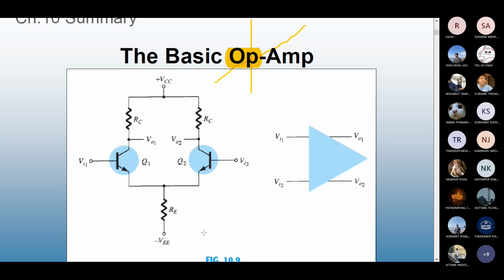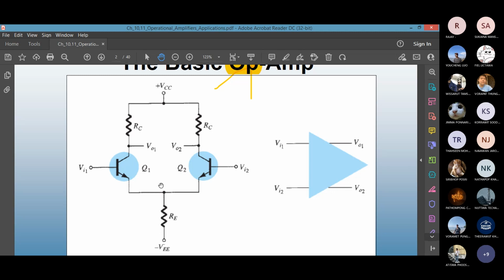Also, when you have the basic differential amp, this is very important. There are 3 input combinations possible. So 3 modes of input. First mode, maybe I have to draw a few things. It is called the single-ended operation. What happens in a single-ended operation? On one input, you have a signal. So I can put a symbol of a signal, and the other input is grounded. This is called single-ended operation for input mode, not the output, input.